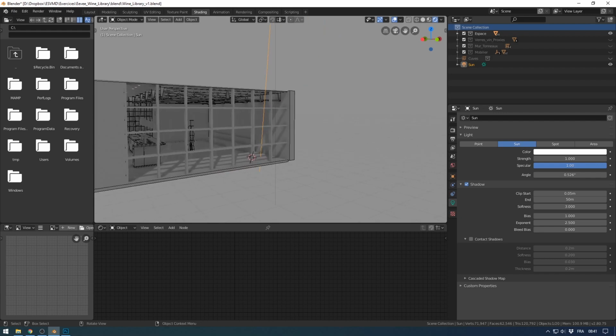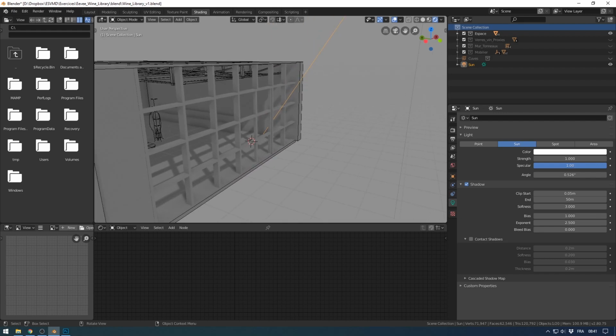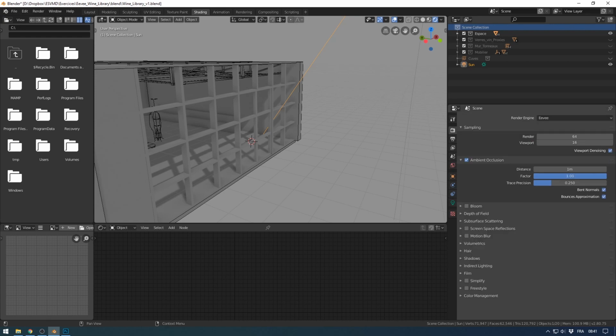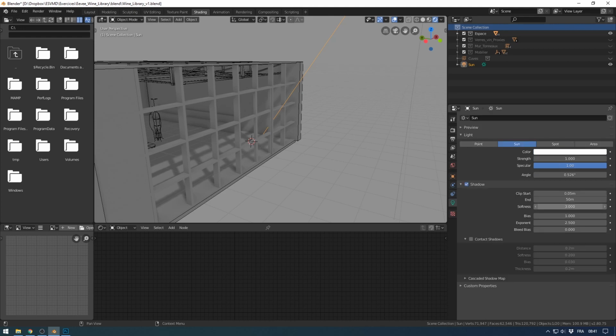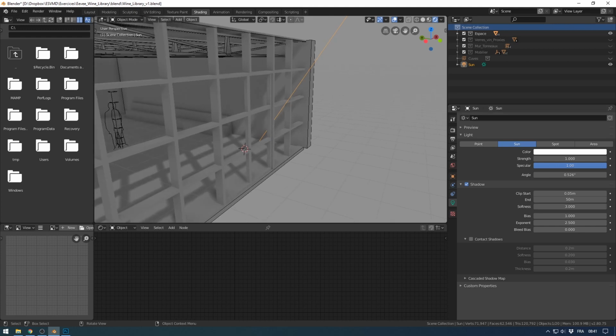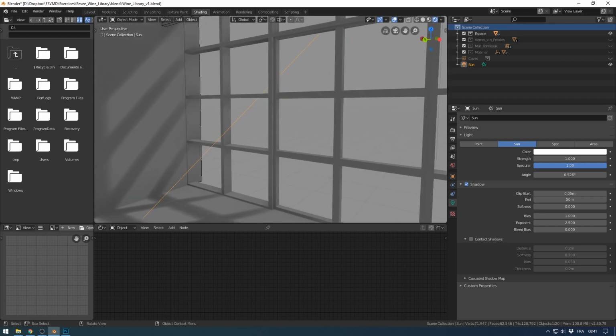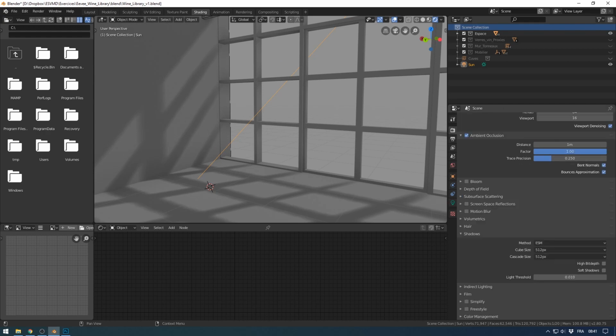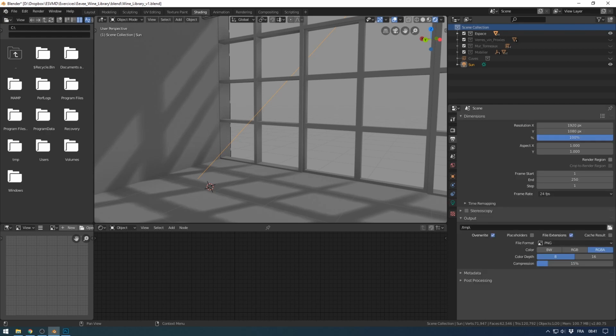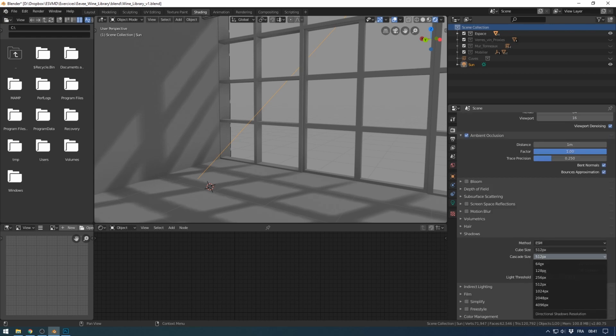The second thing to take care of for the sun, but also available for all lights, is the Cascade shadow setup in the render settings. Cascade size I set to, in my case, 1K, but sometimes a lower value. But you will see that if you would like to make hard shadow or to tweak the softness of the shadow, and you set it to maybe 0 here, you won't get something better than that. And it's probably because the shadow Cascade size is too low.